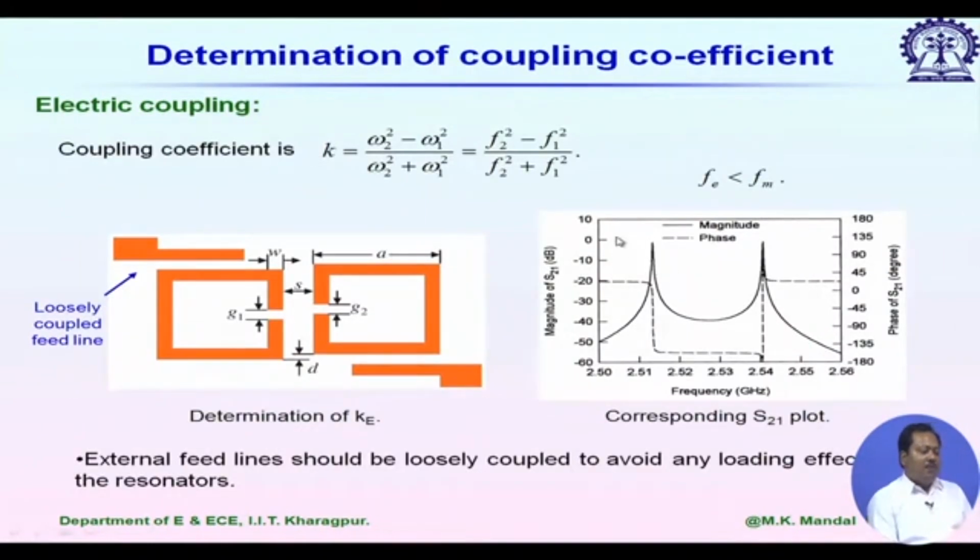Now, how to determine this coupling coefficient? By using any full wave simulator. You see we are using the same coupled open loop resonator, but we have to excite the resonator to obtain the S21. We can determine the coupling coefficient from the S21 plot.